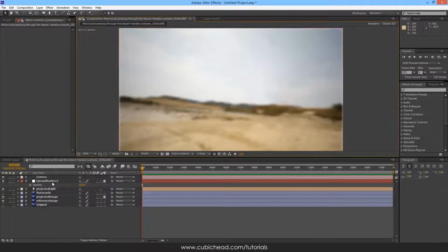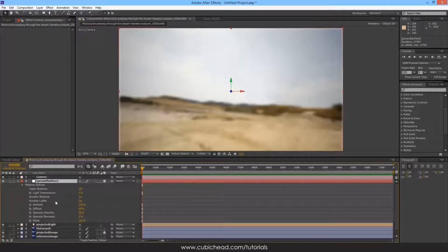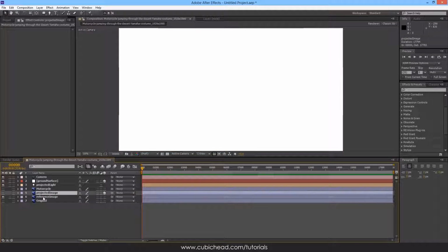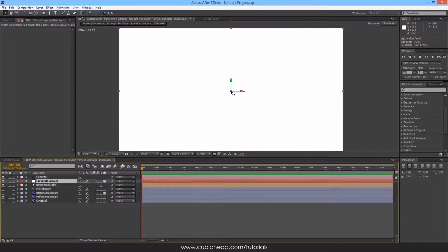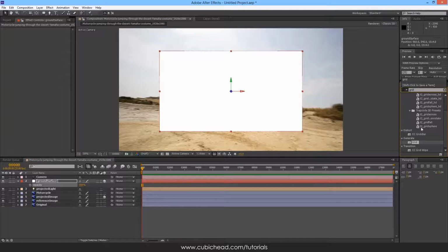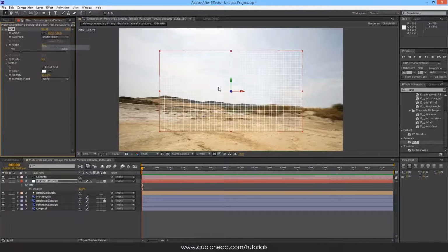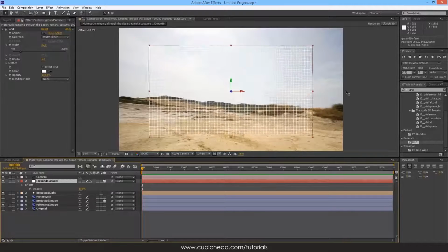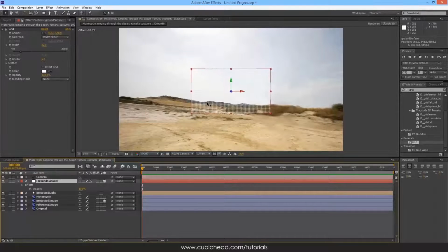You see, instead of seeing a black shadow, you're seeing the actual image, which is casting shadow. Now that you would be seeing it, let's keep on and come to the properties of the ground surface and turn the accept lights off. So again, it won't affect the light, won't affect the projected image on our surface. Now that we have set up our scene, we check this to hide the projected image and use the reference for our positioning of the planes. To position a plane, you could decrease the opacity and change the location, or you could add a grid effect. So you would be seeing the perspective well enough. If you want to change the location using the gizmos here, if it's going really slowly, just hold down the shift key to shift the movement.